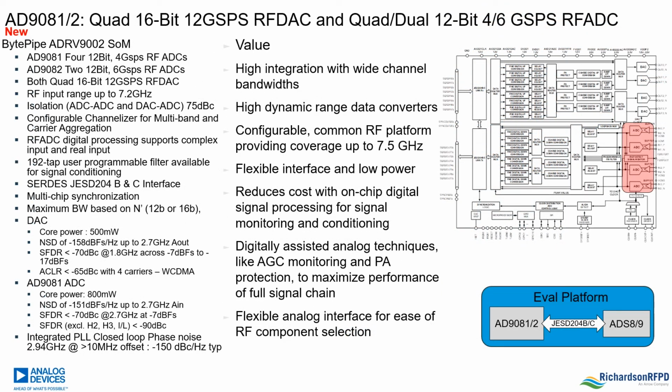Two compatible systems to the UDA24-0440 are the Analog Devices AD9081 and AD9082 eval platforms. Although I wouldn't define the eval platforms as design accelerators, many things can be copied from the design to reduce engineers' design effort. The ADS8 and ADS9 FPGA platforms can also interface to MATLAB for software and HDL development.